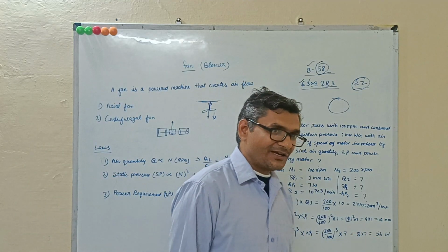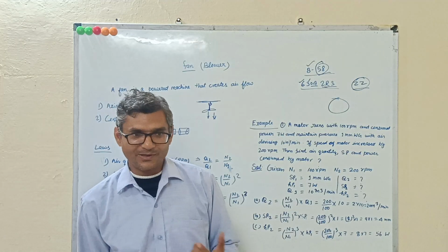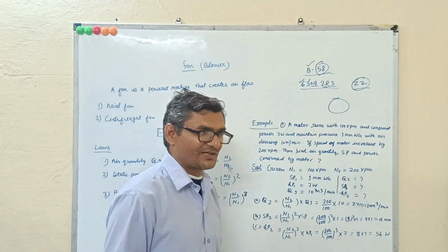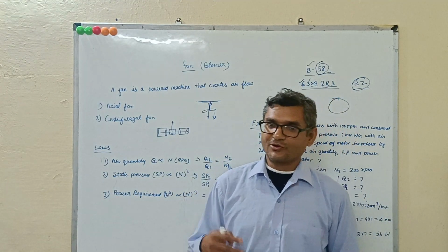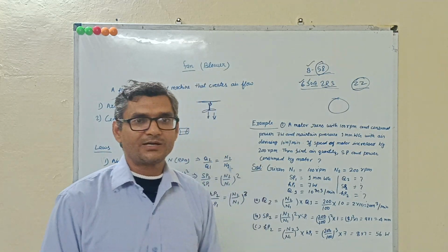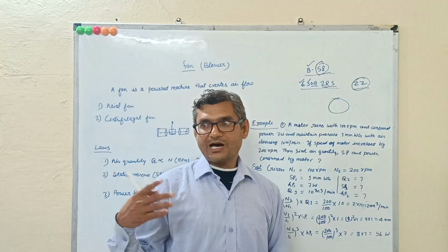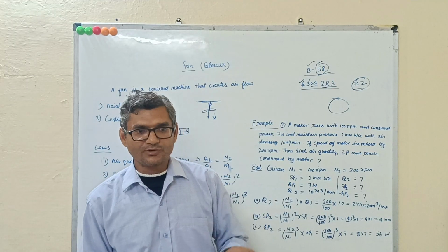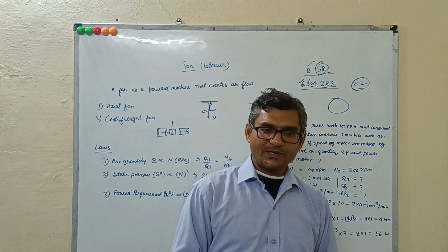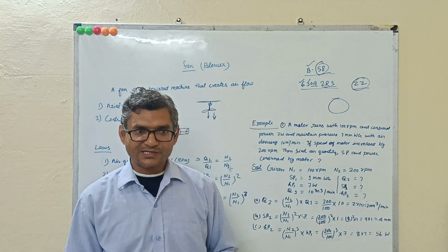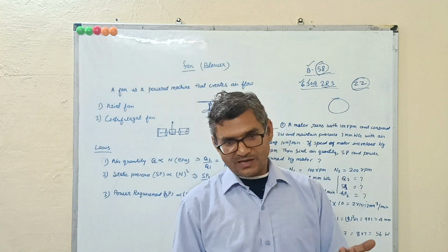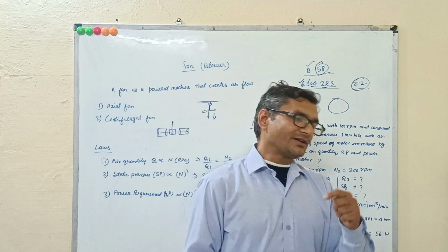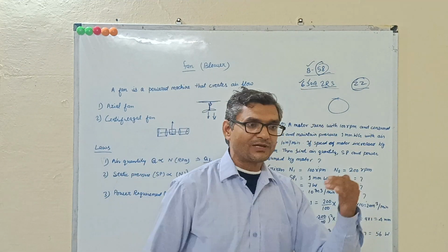Understand how much more. In VFD, variable frequency drive, used in installations now, you have sometimes heard of inverter technology. As per requirement, it reduces or increases the RPM of the motor. If we want to increase air quantity, we increase the RPM, and it consumes more power. When the design temperature is reached, the RPM is reduced, and power consumed is also reduced.